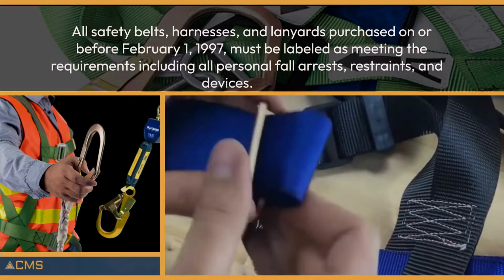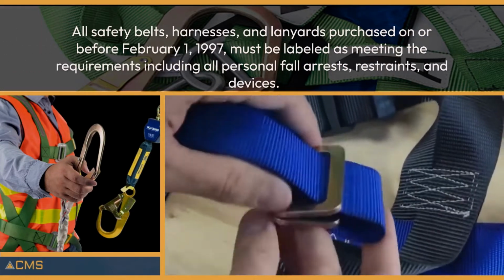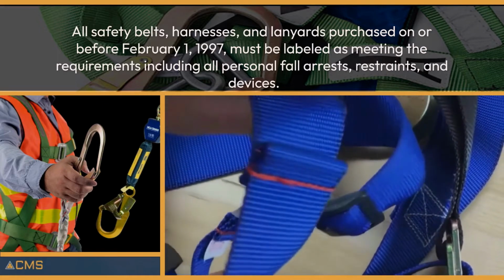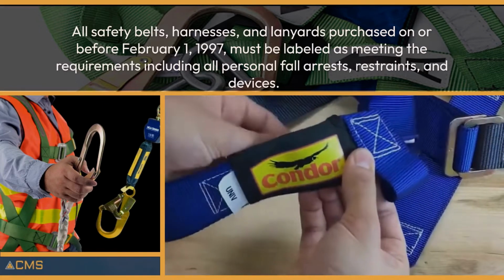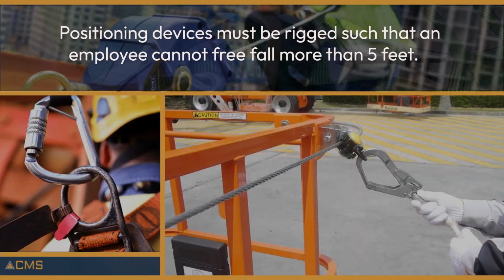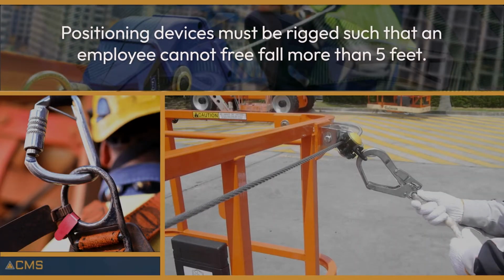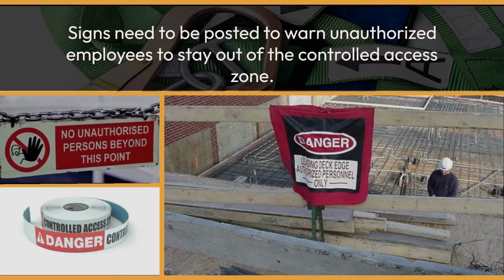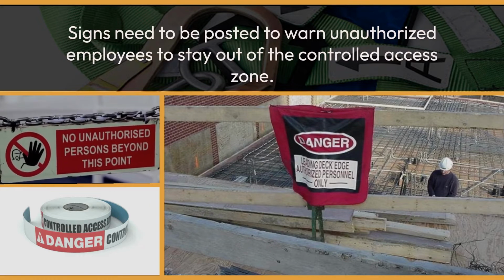All safety belts, harnesses, and lanyards purchased on or before February 1, 1997, must be labeled as meeting the requirements including all personal fall arrests, restraints, and devices. Positioning devices must be rigged such that an employee cannot free fall more than 5 feet. Signs need to be posted to warn unauthorized employees to stay out of the controlled access zone.